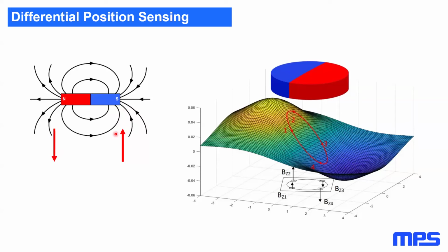The difference is we need to have at least two differential pairs because we need to know, as this magnet rotates, where we're seeing the maximum flux and where we're seeing the minimum flux. And so here, let's take a look down here in 3D. This will be much more intuitive. In 3D, here we've got the die. Here we've got our two differential pairs. They're diagonal from each other.